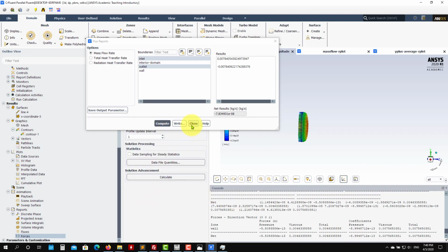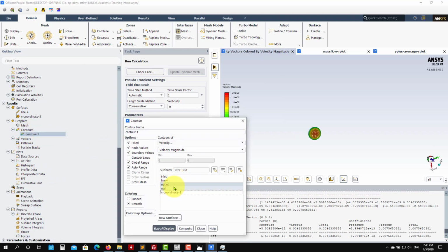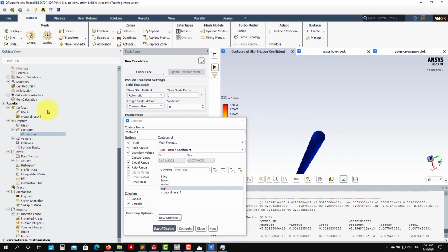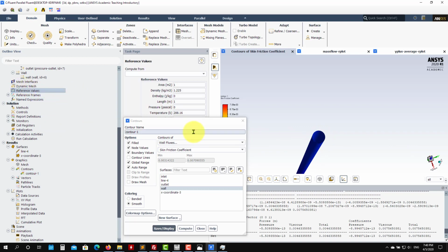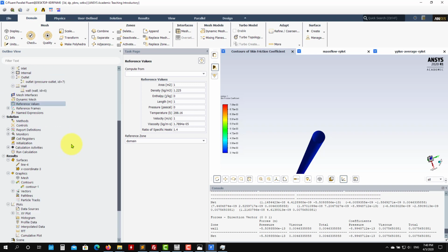By the way, you can access that information as well. Friction coefficients, you go here, wall, to the wall flux. This is what we call skin friction coefficient. Okay, and you have your skin friction coefficient. It is computed, it is normalized using the reference values here. Okay, so you need to input here the reference values to normalize that. It will be the same with the forces, with the coefficients. You compute coefficients here, there are coefficients. This will normalize using these quantities. Okay, so you should do this manually. Okay, Fluent doesn't know that.